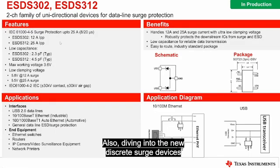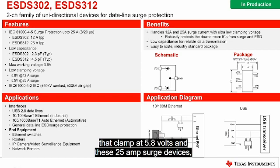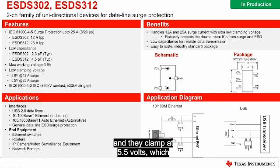Also diving into the new surge devices, the discrete surge devices that we released, we have these 12 amp surge devices that clamp at 5.8 volts and these 25 amp surge devices that clamp at 5.5 volts, which is extremely low for these devices, and can protect almost any downstream device like this USB transceiver or the Ethernet PHY, as long as they can support the capacitance.